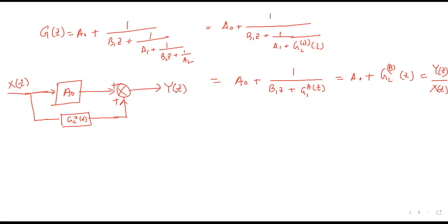Okay, so now this has to be G1, because already we have taken G2 here. So this is G1. So now how can we represent G1? We can see that G1 can be represented by the fact that we have to divide by B1, 1 by B1, and then we have to multiply with the next gain in the feedback.